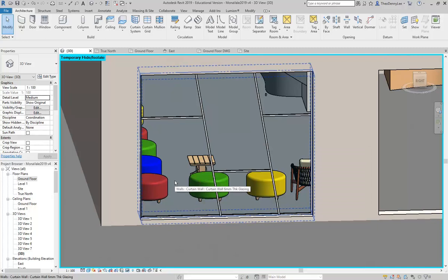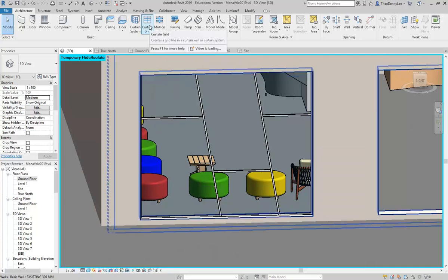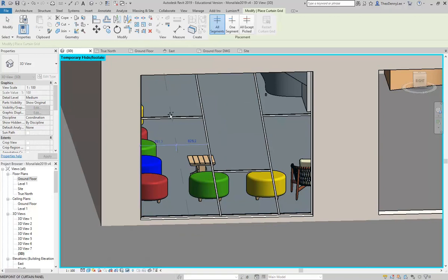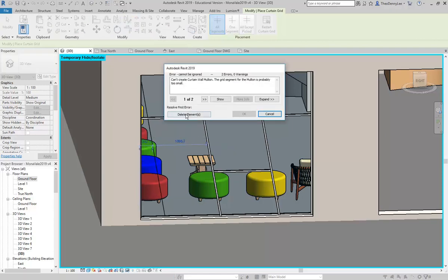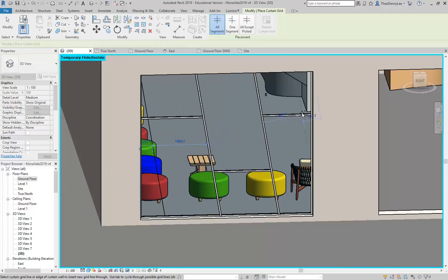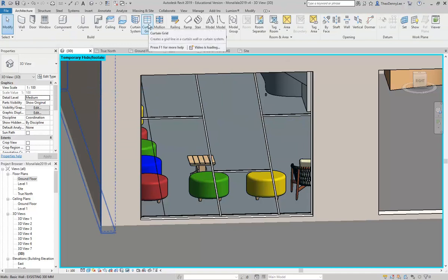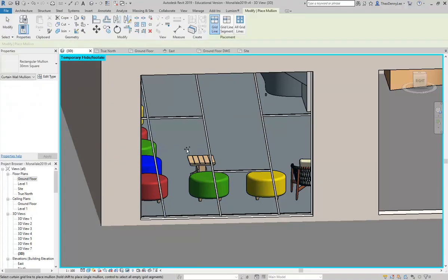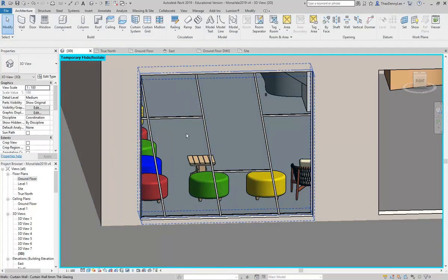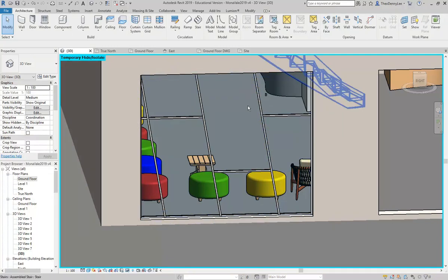And so you've got to remember though that even though you can change the angle of those axes, the other grid lines following that axis need to be parallel to it. Right, so you can see I've gone to put in some new grid lines, and they have to be parallel. So I can still put mullions on that, of course, but just so you can see, these grid lines that were vertical, now, even though they're angled, are still parallel. They have to be.